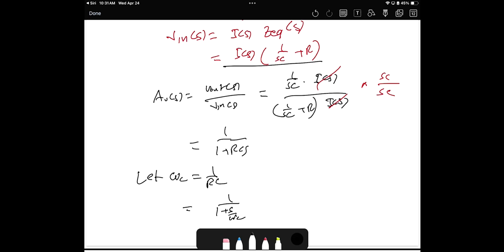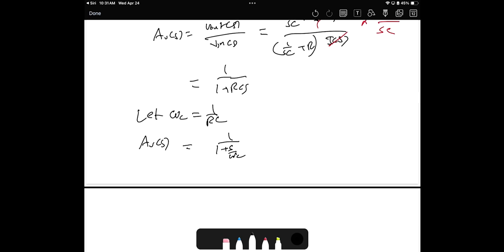So this yields to this transfer function. Now we need to do the Bode plots. The first step is to do what we did here: when you see a circuit, convert this circuit into the transfer function. If the transfer function is provided to you, then you can skip this step and save time. But if you don't have the transfer function, you need to find it.